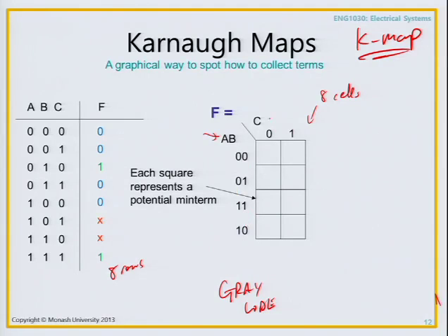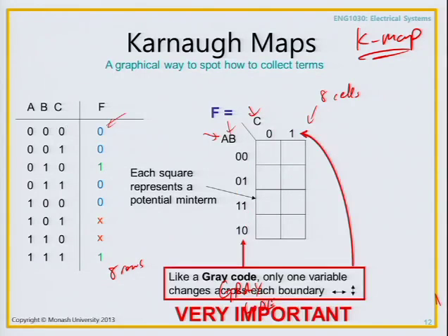And now that we've mapped out, the first part is to get this right. The second part is now to transfer the outputs in the truth table into the Karnaugh map. So that first row, A equals 0, B equals 0, C equals 0, would go into this. This is just emphasizing the importance, because it's in big red font, of putting this in Gray code.